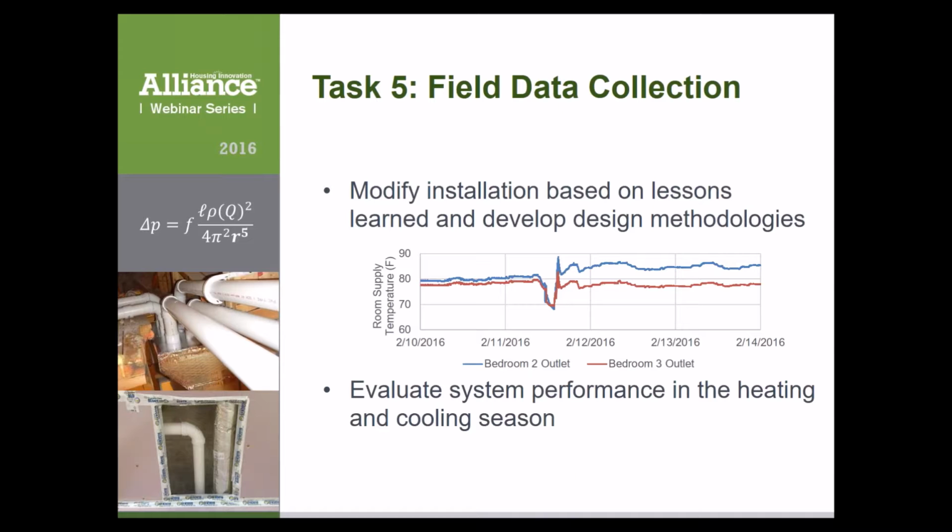One of the things that's going to be critical in ensuring comfort is delivering air at the temperature that you need. That will also help prevent the air from feeling drafty. These measurements and observations are influencing our decisions with the design methodology and with the duct material. We'll get into some of that in more detail later. We are measuring data in both the heating and cooling season. The climate is Pittsburgh, generally considered more of a heating season, but the cooling season data is very valuable as well.